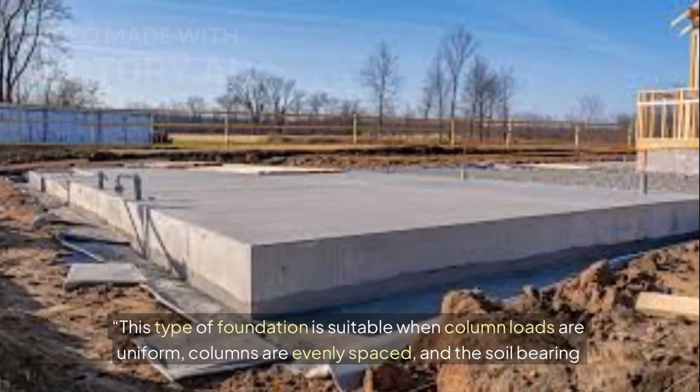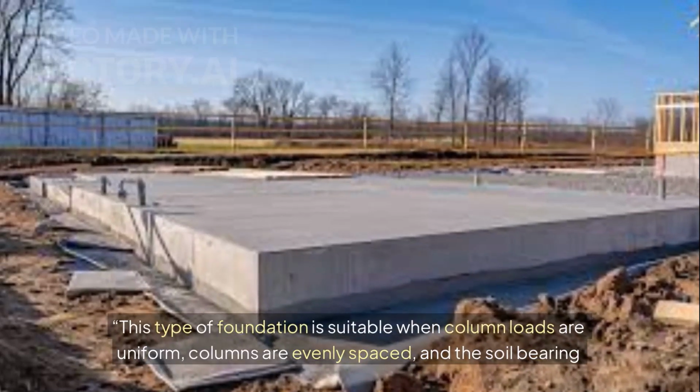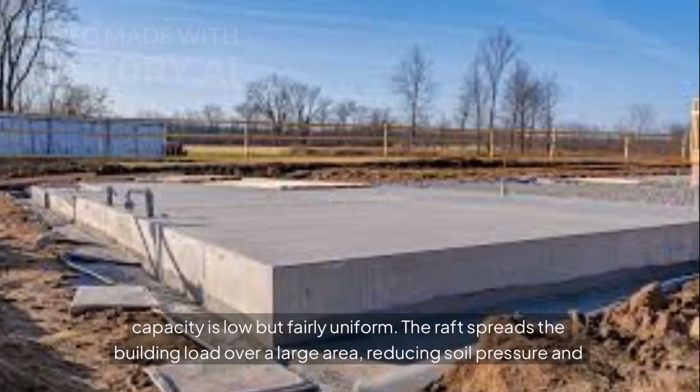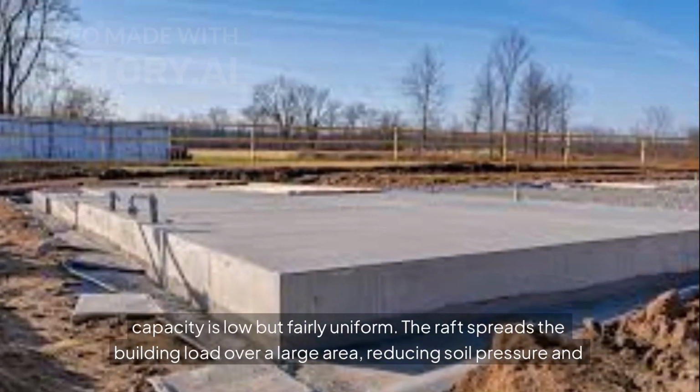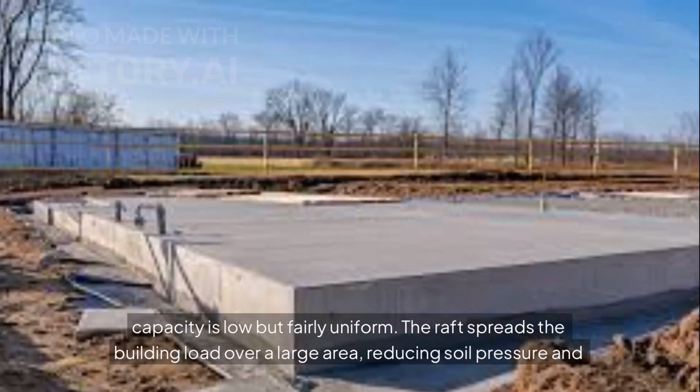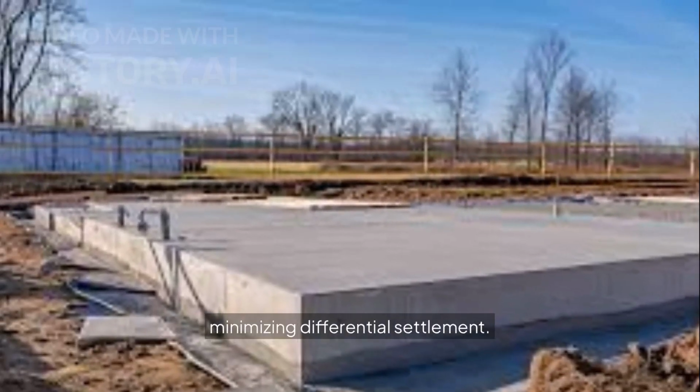This type of foundation is suitable when column loads are uniform, columns are evenly spaced, and the soil bearing capacity is low but fairly uniform. The raft spreads the building load over a large area, reducing soil pressure and minimizing differential settlement.